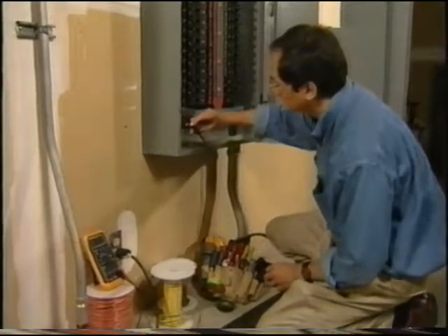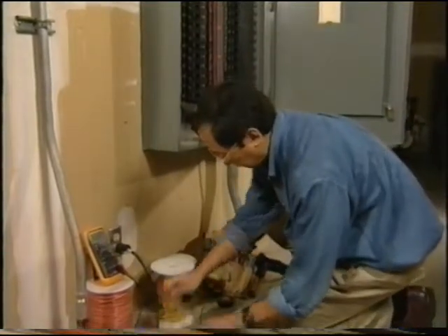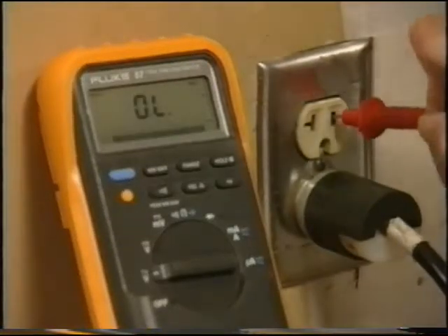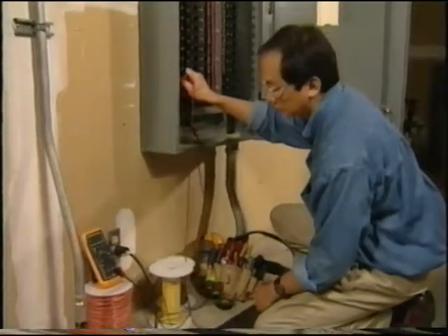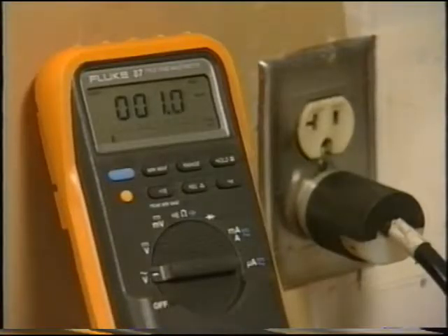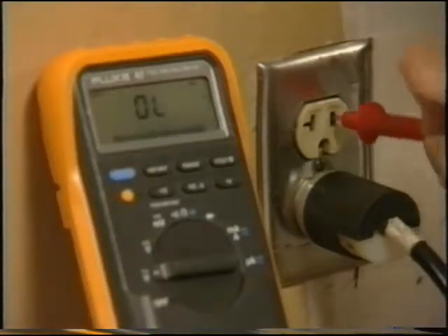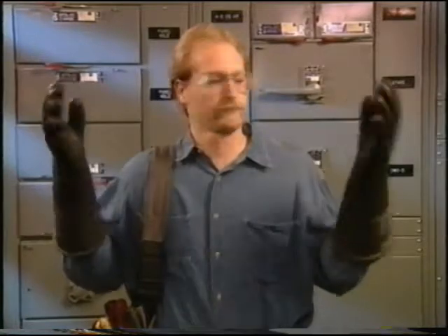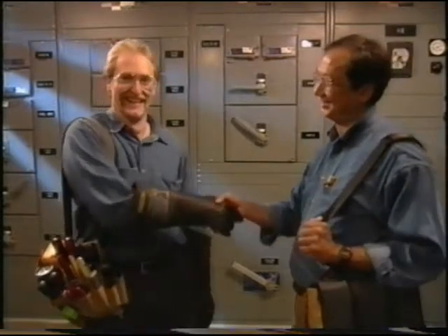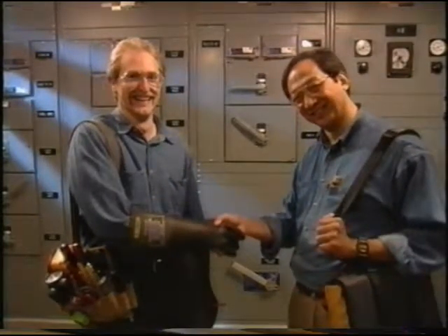Use the three-point test method to make sure your meter's working. To do this, first test a circuit known to be live. Measure the target circuit. Before concluding the circuit's dead, retest the known live circuit. This way, you know your meter's working. Use well-maintained tools and appropriate safety equipment, including safety glasses, insulated gloves, insulated tools, insulating mats, and don't work alone. These are just a few tips to make your measuring, troubleshooting, and repair go smoother and safer.